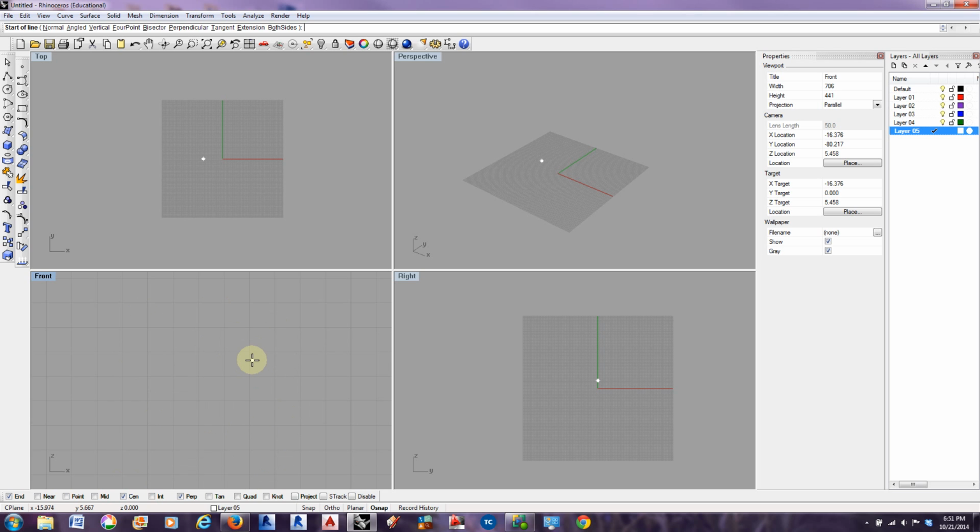So we've gone through the toolbars briefly, the command line. Did we actually talk about the command line at all? Not really. The command line is similar to the command line in AutoCAD. So if I were to escape here and just start typing in line, it'll bring up every command it knows that starts with those letters. And so instead of using the menus or the quick select keys here, you can start to type things in directly into the command line.